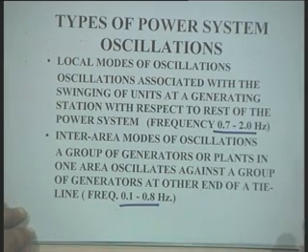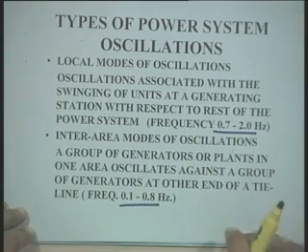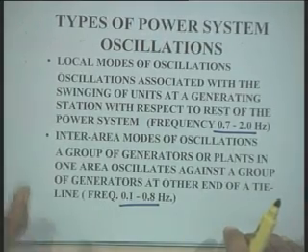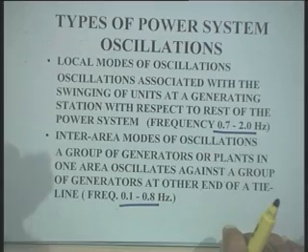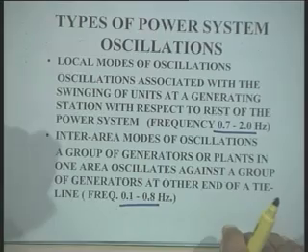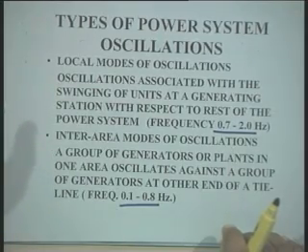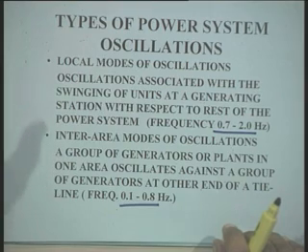And the phase lead controller is to be designed so that we get the required phase compensation. But as we have seen, you can design this phase compensator to compensate exactly the phase lag of the system at one particular frequency. Now, further we have to understand very carefully that the phase lag of the system is not constant.